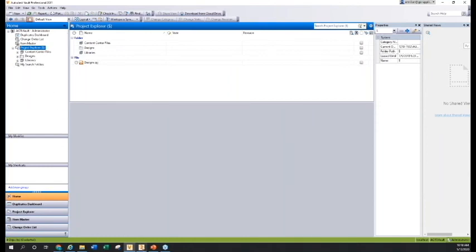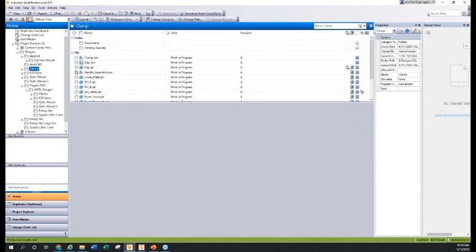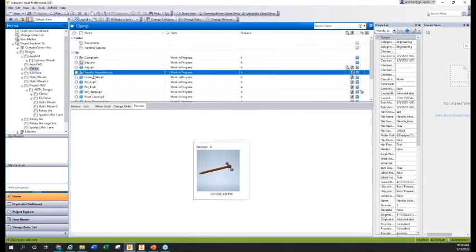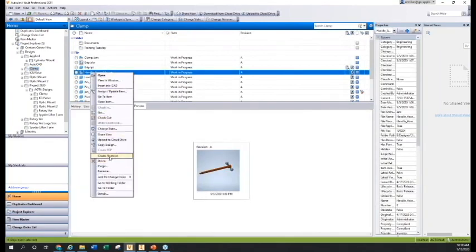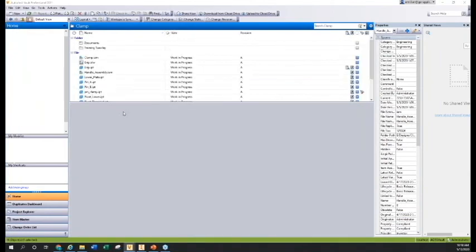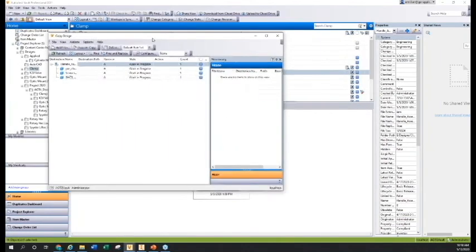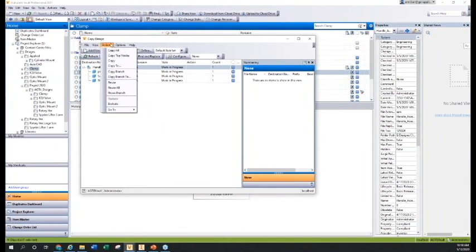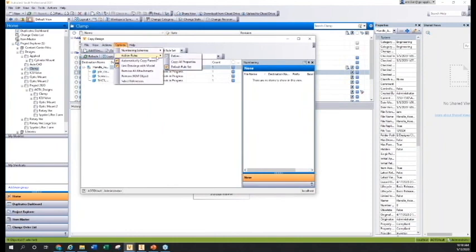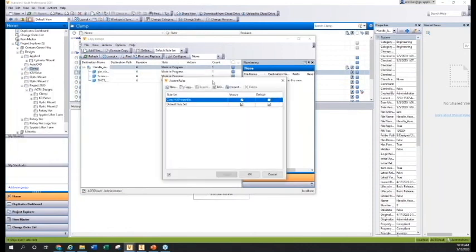All right. Let's see. So we looked at the has parent. Okay, let's look at just a couple more things here, maybe just another minute or two, but I wanted to show the copy design function. So if I'm going to take maybe this handle assembly, let's right click, do a copy design on that. And here's my window. So if we go into the action, let's see, options, action rules, let's go define. And dragging that over here too. Let's go a new rule.